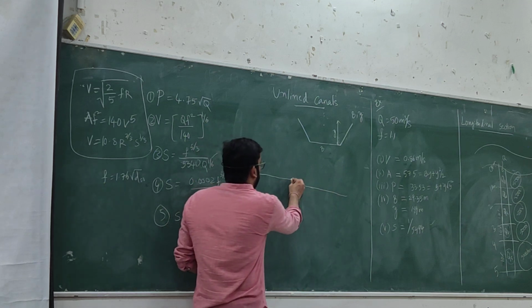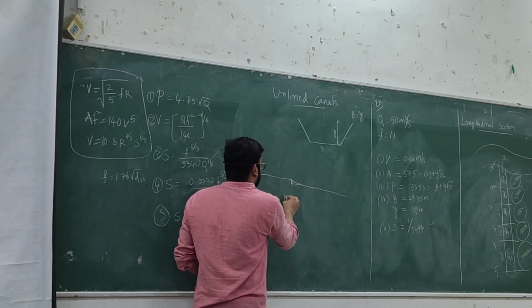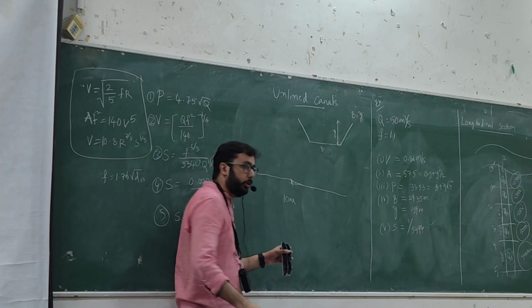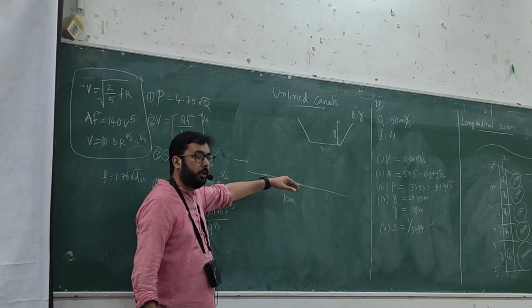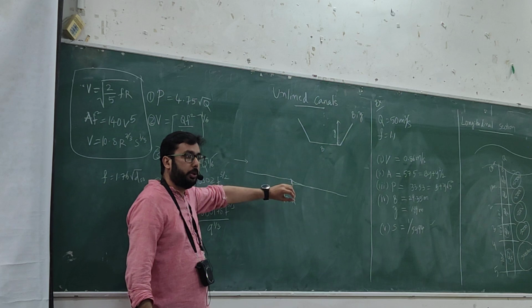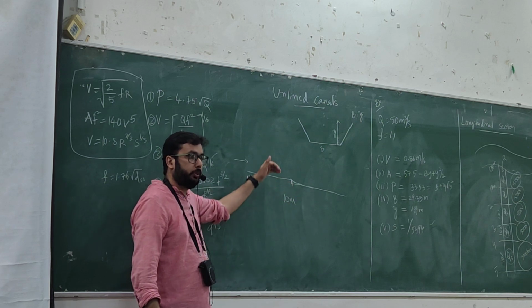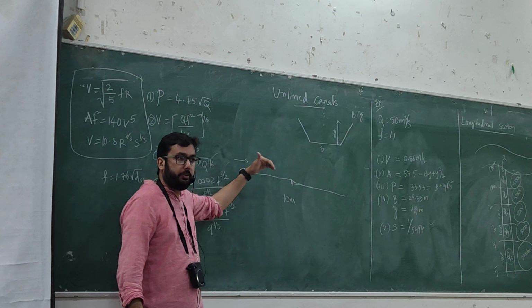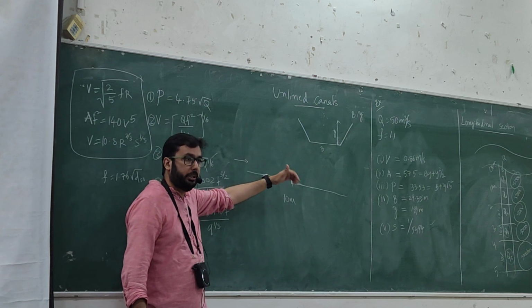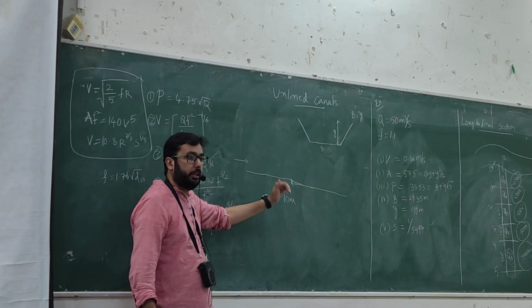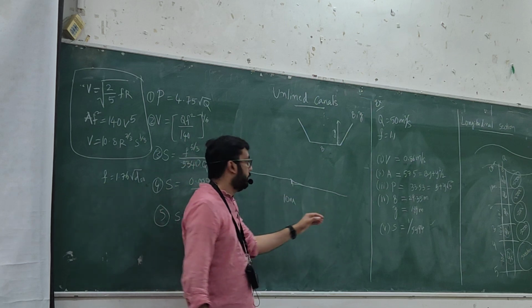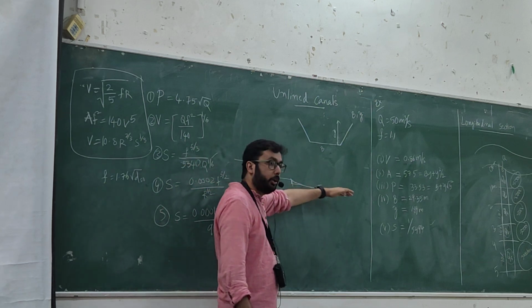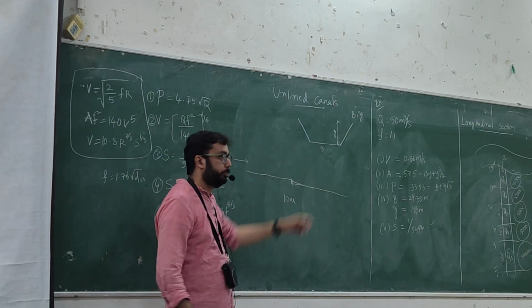If this fall is higher, let's say 10 meters or more, then we can have a small hydropower plant, some small turbine you can use there. Because it has a 10 meter elevation difference, you can divert the water through the powerhouse, generate some power, and then let the water flow again. So this is how the longitudinal section might look if you have changes in the elevation.